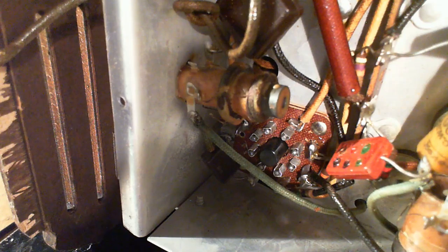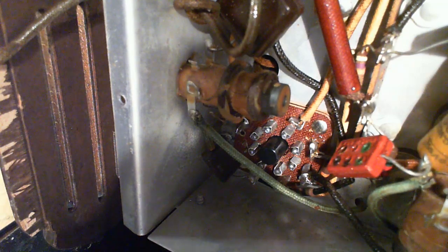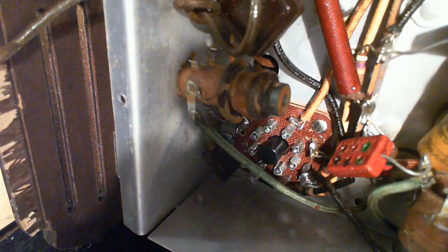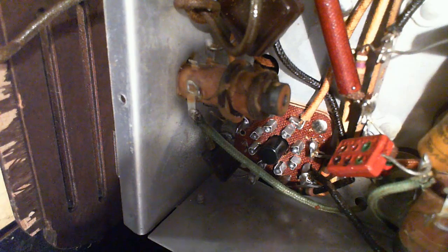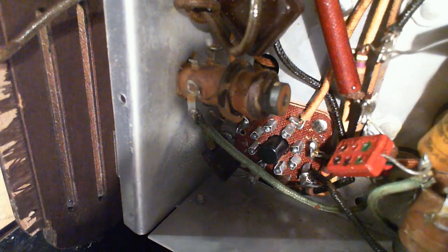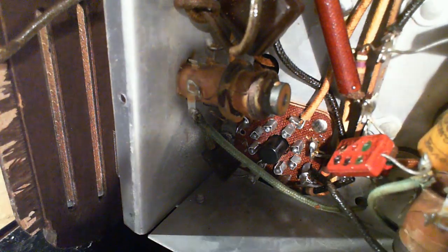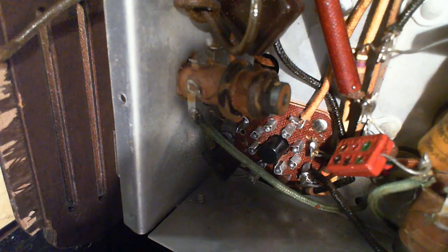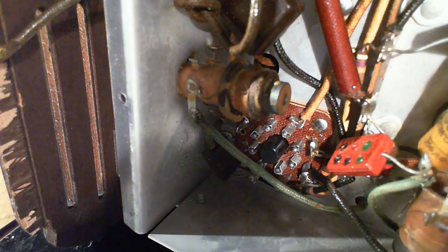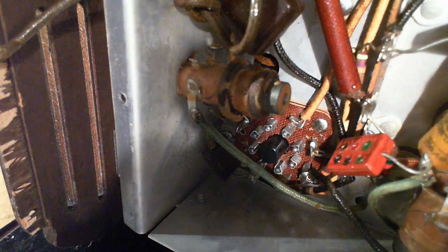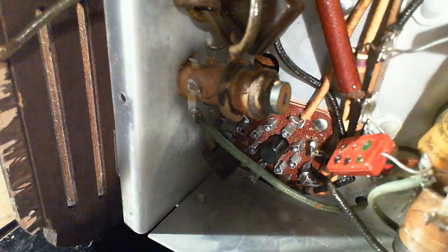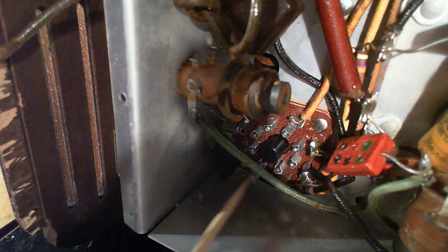So what can we do with this guy now to check him out? I can see where the secondaries are. Get a clip right on the secondary with my scope or something like that. Pump a signal into the antenna. I think at that point I've just made the circuit so different from what it is when it's operating normally. The secondary, so there's that capacitor that goes to the tube, and I talked about getting on the other side of that capacitor. That would be down here. Why don't we start with that?